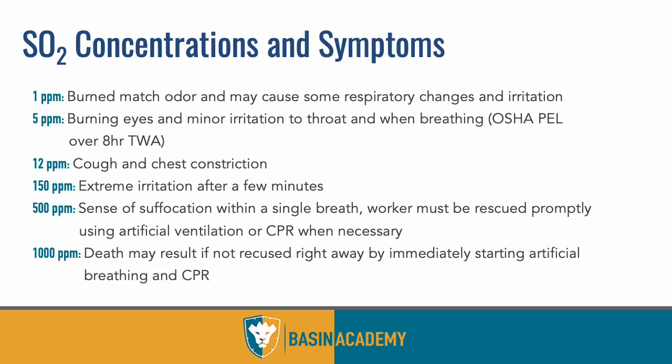So again, from 1 to 100 parts per million is kind of our danger zone. Above 100 parts per million is where we're really going to start experiencing those higher issues, those acute sicknesses. And then over 100 parts, which is the IDLH for SO2 as well, that's where we're going to see permanent damage being caused by it. And then it's kind of a crapshoot, depending on your personal exposure, susceptibilities, etc. Just like H₂S, although SO2 is a little different, between 500 and 1,000 somebody can be instantly dead, or DRT. It just depends on the person.